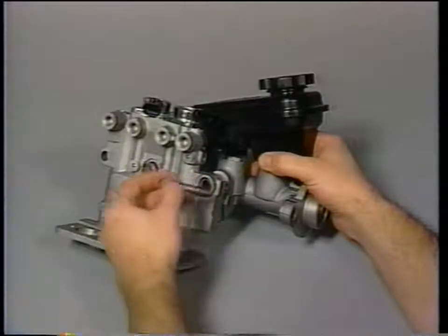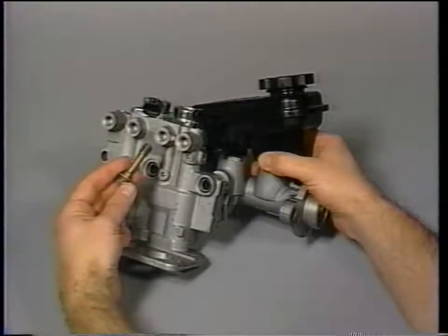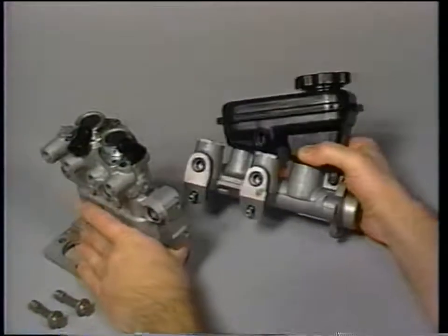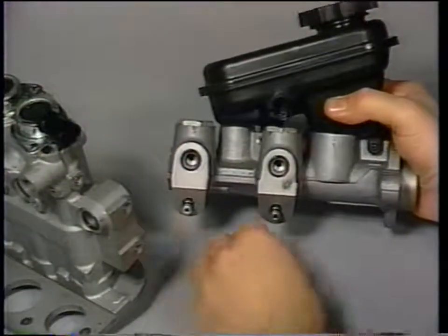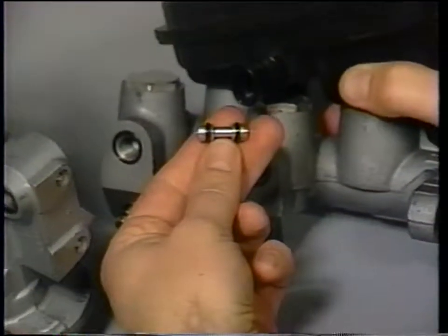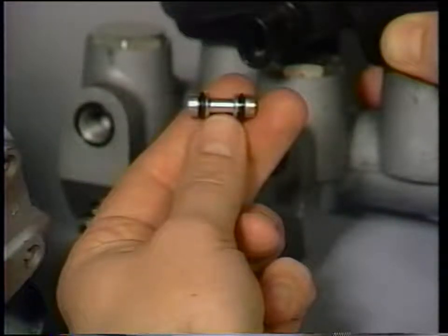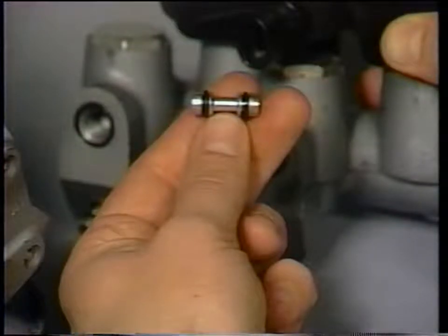Attached to the master cylinder is the hydraulic modulator and motor pack assembly. The modulator is held by 2 banjo bolts at the master cylinder's 2 upper outlet ports and 2 transfer tubes at the 2 lower outlet ports. An important service point to note here is that the 2 lower transfer tubes and O-rings must be replaced if the master cylinder and modulator are disconnected from one another. This is necessary to prevent leaks that could cause the brakes to fail.